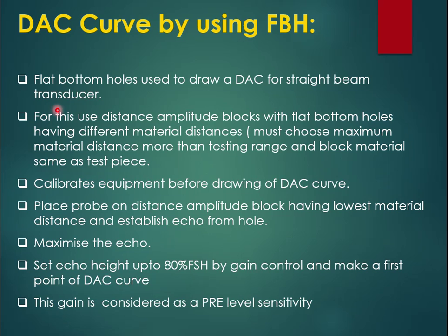If the sound travels at some angle, we consider them angle beam transducers. So basically, flat bottom holes are generally used to draw a DAC curve for straight beam transducers.